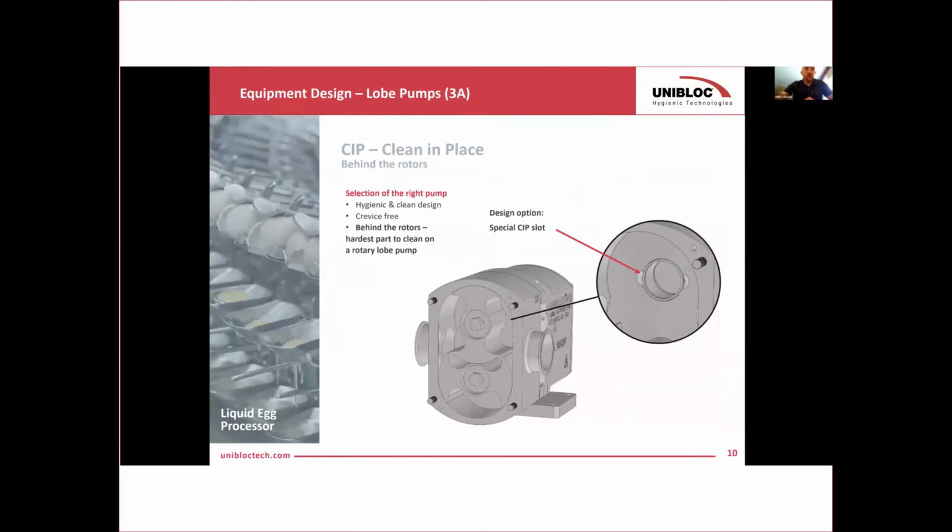As I mentioned before, another part of the pump that is difficult to clean is the area behind the rotor. The reason for that is because of such tight tolerances. There is not a lot of gap behind it for the CIP fluid to go behind the rotor and properly clean out that area and the seals that are then positioned behind the rotor. But there are